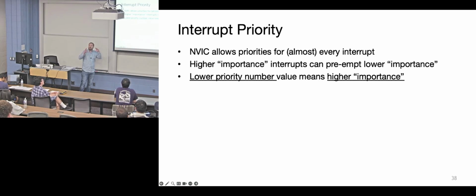Because remember, the number of interrupts that can occur is defined not by ARM, they only provide 16, but also by the manufacturer, and you can have up to 240. So your particular dev kit has 96, I believe. So the problem is you never know what the absolute number of interrupts on your chip is, so you just go reverse order, 0 being the most important.